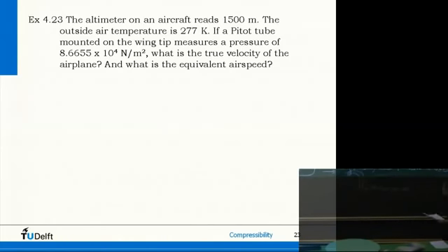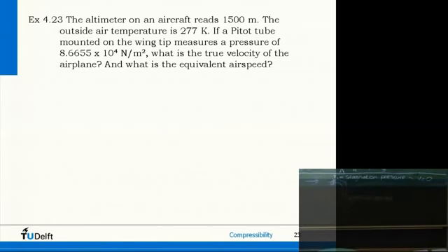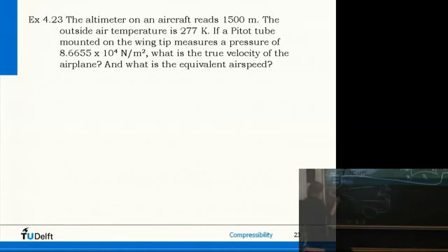We also have pitot static tubes, and that is connecting this one to another with typically a manometer. Suppose you have a channel, you connect this, again a differential pressure gauge now, to this tube. In this way you can measure differences, right? So here you can measure total pressure, and here static pressure. Why does it measure static pressure here? Well, this tube doesn't fill up. The flow goes just past it, and inside the tube the pressure locally at that point is felt. So you have the static pressure and the total pressure, and a differential pressure gauge, so this one measures differences, right? So you have information on P0 minus P static at that location.